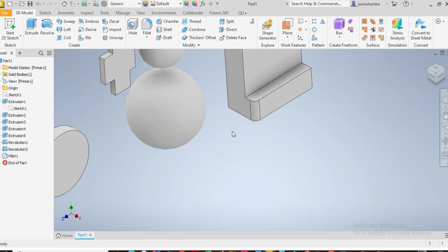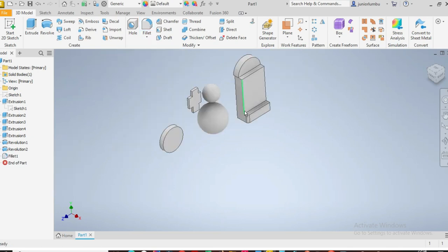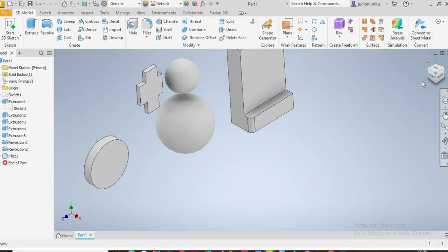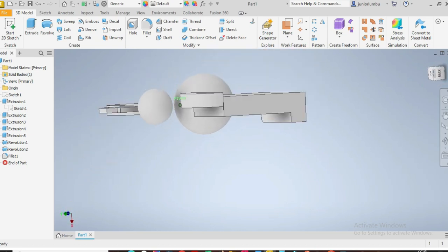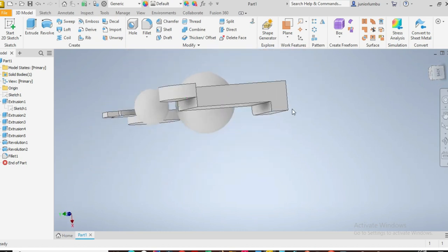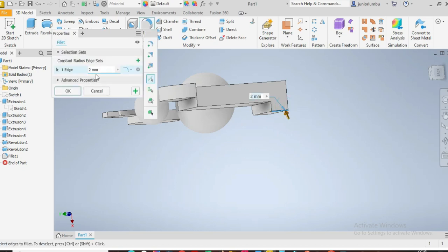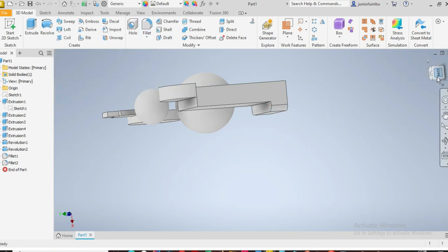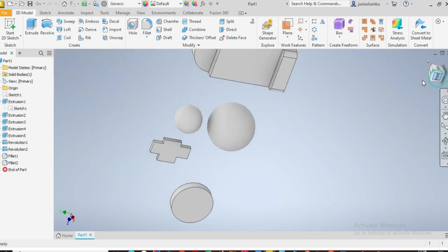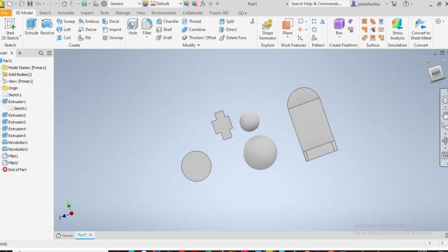The same way, you don't have to click on the tool there. You can also come on the corner. By doing this, I come there, I click on there, then I have the fillet option. I can choose my radius. This time I'm going to say 30mm radius, then I have my fillets there. So now, this is how you turn it.